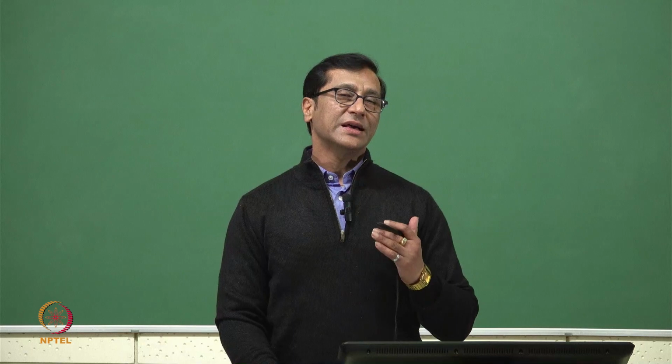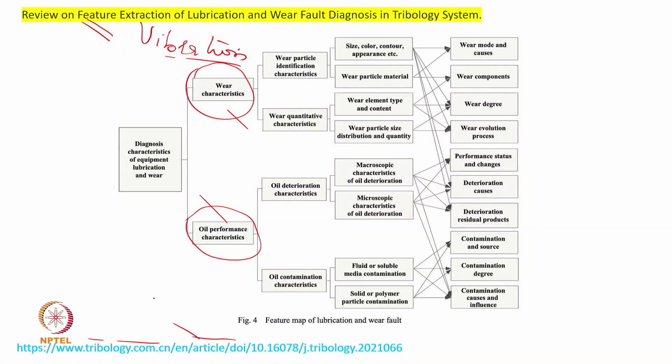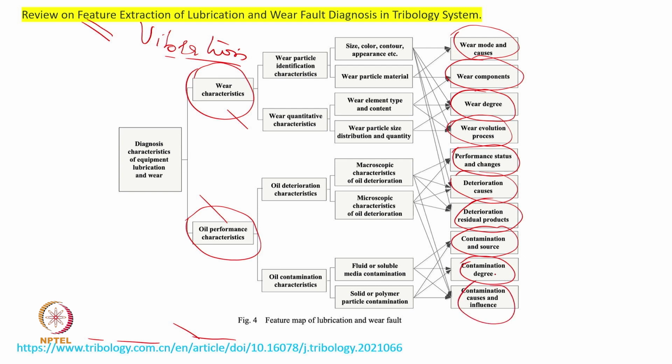We did a vibration analysis, wear analysis and oil analysis, and here in this paper they use a wear analysis and oil performance analysis. What they are trying to figure out: what are the wear mode and causes, what are the wear components, what is the wear degree, the severity level, what is the evaluation process of the wear, what is the performance, what is the deterioration, and then what are the residual products, what are the contamination level, what are the degree of contamination, what are the causes. So these are the things from which they are trying to extract the features.